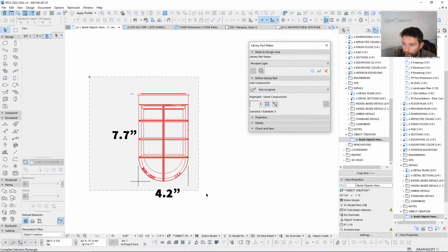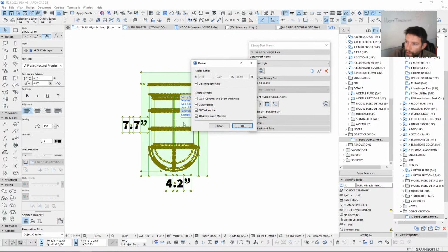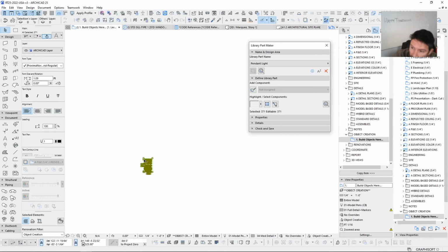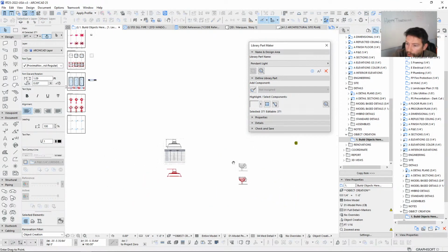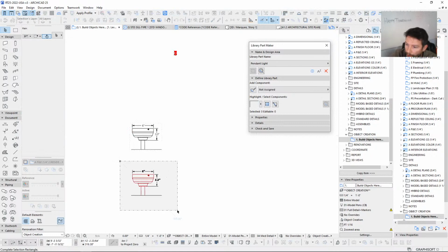So next step here, we are going to take these, and I'm going to use a Control-K command to graphically define our distance here. So I can see that's 4'10" right now. We're going to take this and we're going to set this to 7.7 inches. And so now we have our guard at the correct level. So I'm sure we're going to be kind of compressing all of these down, as we can obviously see.